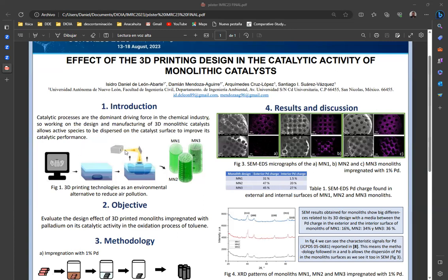Catalyst fabrication is a promising area for 3D printing, as printing processes result in better control of the structures and distribution of active sites in the catalyst. In this sense, there are several 3D printing techniques such as extrusion printing, direct ink printing, vat photopolymerization, stereolithography, among others. However, from the high-precision printing techniques, stereolithography allows printing reactors and lab-on-a-chip devices like the monoliths that we are printing for this work, for efficient chemical reactions with reduced absorption of reagents.